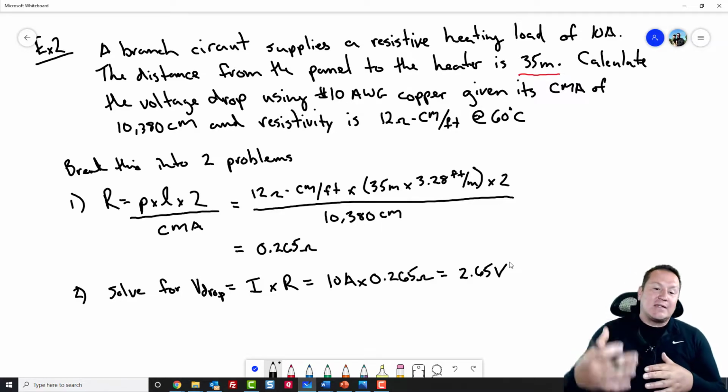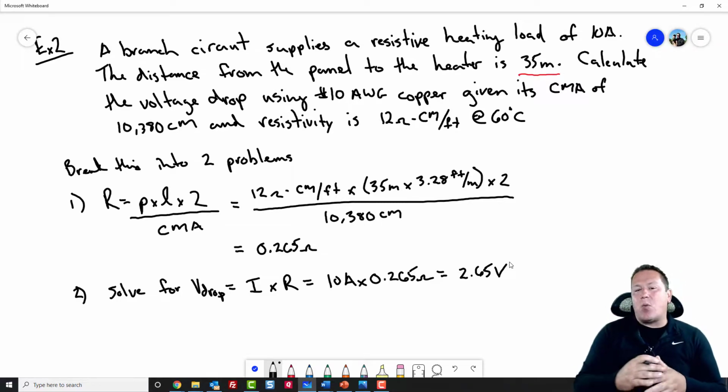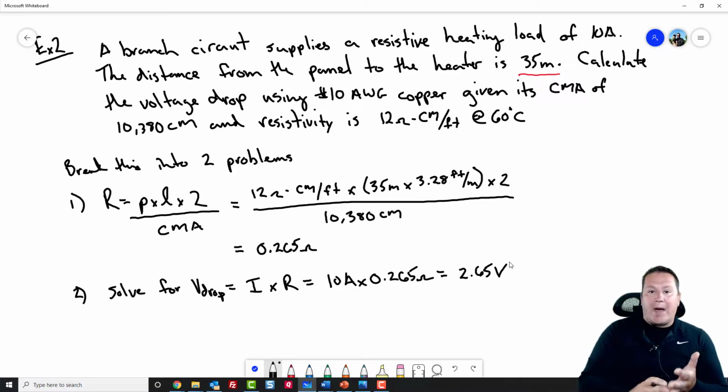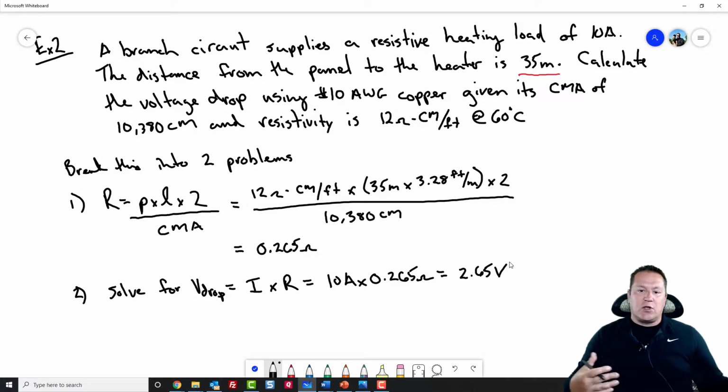However, in the next couple of videos at least, I want to get into how to analyze a circuit like this, where you have a single phase 2-wire circuit feeding a load. You have a given resistance of the conductors, the power being consumed by that load, the power being supplied by the AC line, and how you can calculate the unbalanced load currents traveling on a neutral conductor in a 3-wire system. That's similar to what electricians install every day in residential and commercial installations.